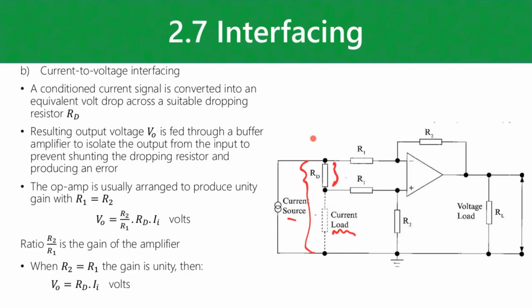And then we have a difference amplifier, or differential amplifier, that we use here. Basically your output voltage is then given by this formula here. If R1 and R2, so both these resistors are R1, and then you have R2 there and R2 there, if those resistors are all the same size, then that becomes 1. Cool, then that simplifies your equation a little bit there.